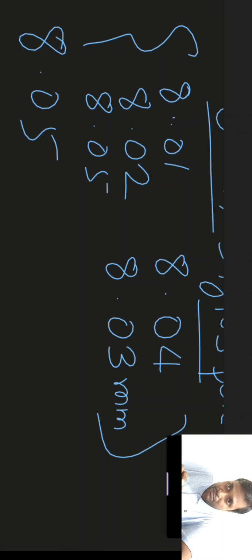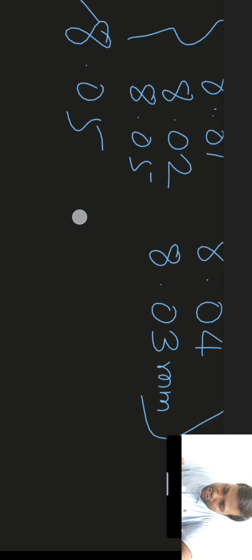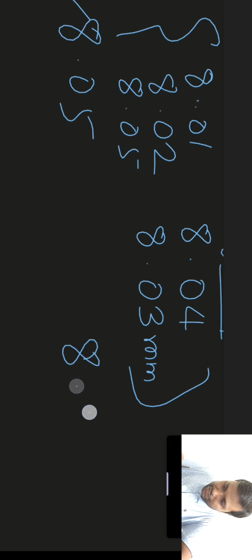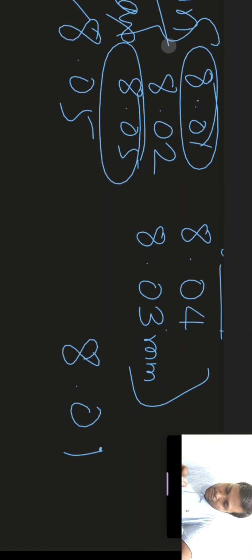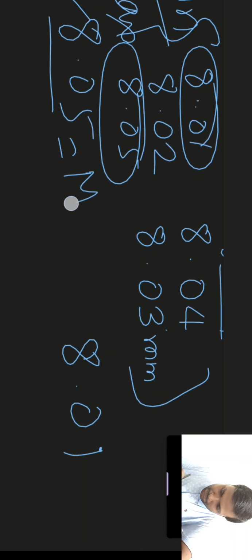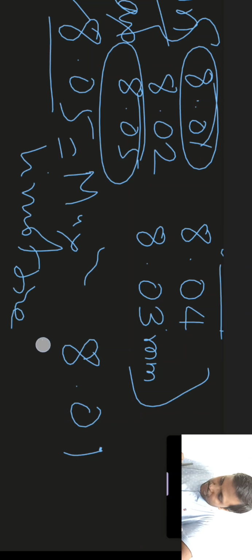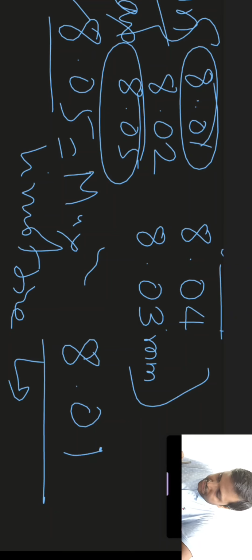The pen which has the maximum dimension will be 8.05 mm, and the pen with the minimum dimension will be 8.01 mm. So 8.05 will be called the maximum limit size, and 8.01 will be called the minimum limit size.